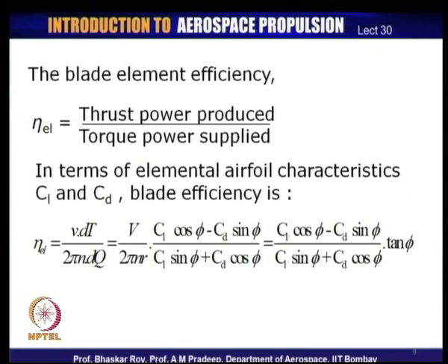So, this aerofoil section is operative in a particular situation, which is incident flow at an angle of phi, and this of course creates the local aerodynamic flow angle, which creates a lift and the drag, and they together then finally decide what is the efficiency with which this element is going to perform. So, we can directly calculate the elemental efficiency from the aerofoil characteristics and the local flow condition.